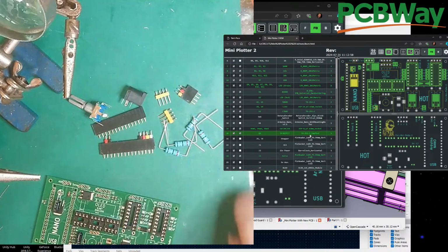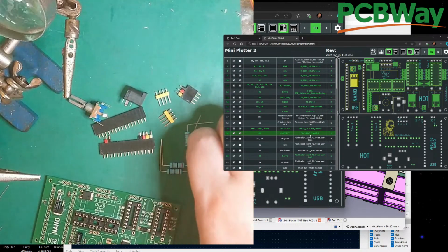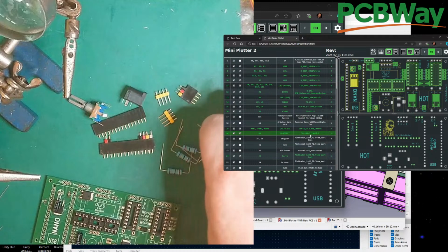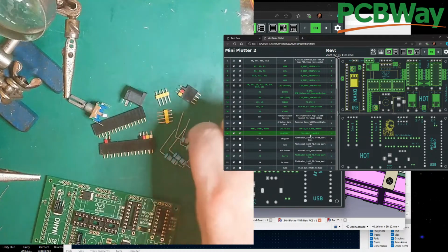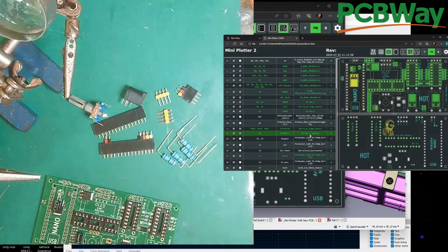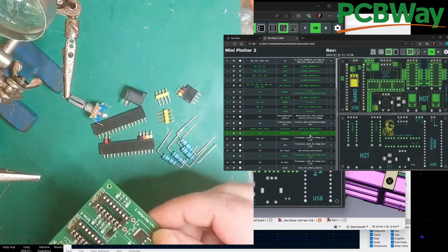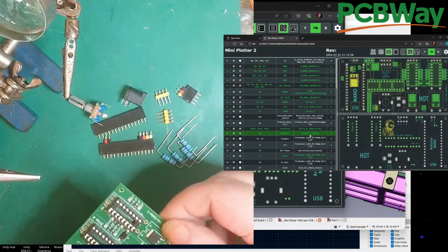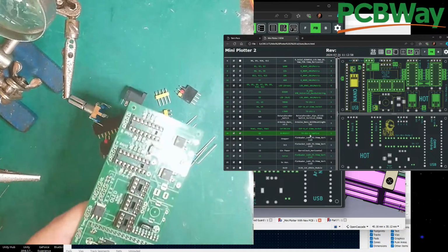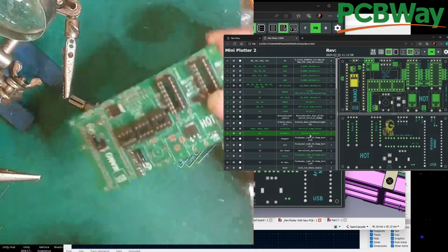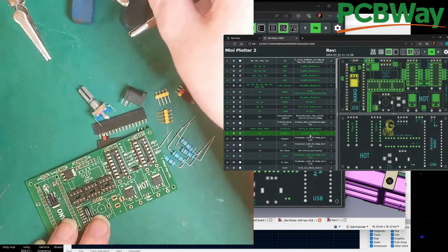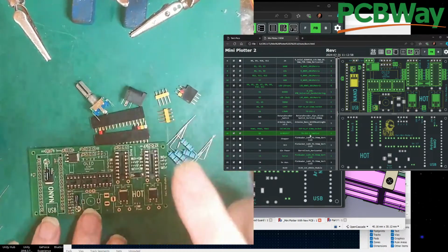Can you see all them bits? Right, so these are all my resistors. I'm using 24 ohm. These are 1 watt. It's what I had. Really, I should have used, I was thinking about buying some 2 watt ones. Really, so then you end up with like 4 watts at 12 ohms. I've put room for 4. You can either put 1 12 or 2 24s in. It's entirely up to you. So it is what it is. So yes, that was it.